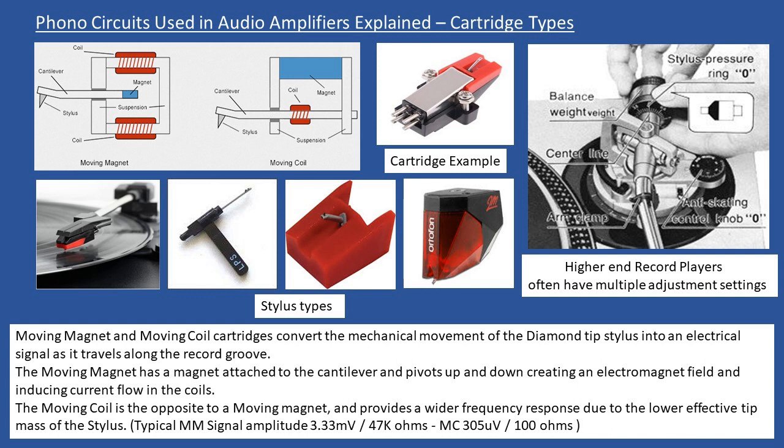What I'm saying here is, if the gram pressure is too light, what you could find is that the stylus then skates across the vinyl record. Very clearly, you want to avoid excessive weight, so that it's pressing down too hard. On early record players, they were kind of fixed. If you wanted to increase that, and I grew up seeing this, sometimes people would put a small coin on the front head where the stylus is and just tape it on there, just to add extra gram weight. On more modern record players, you have a wide range of settings, and I'm showing this here in the video.